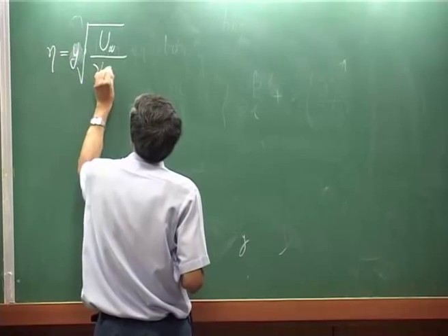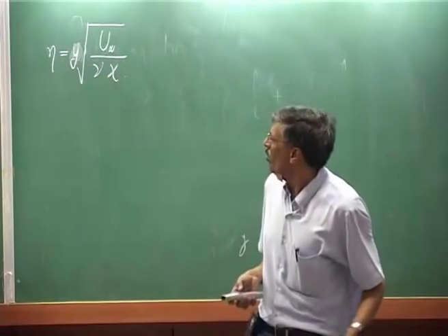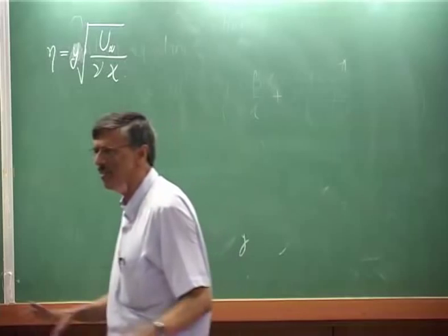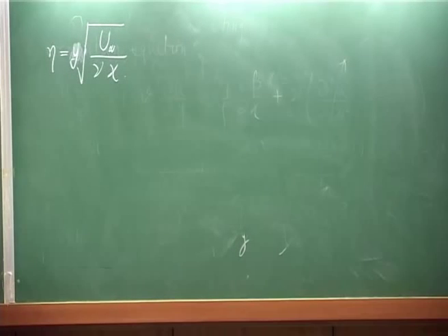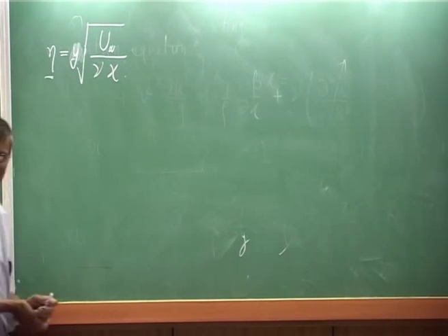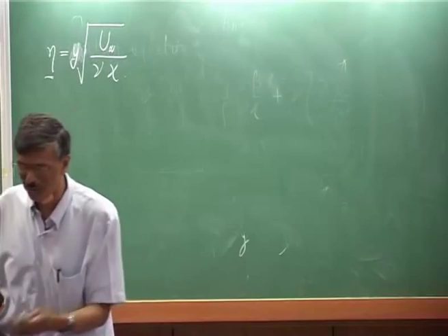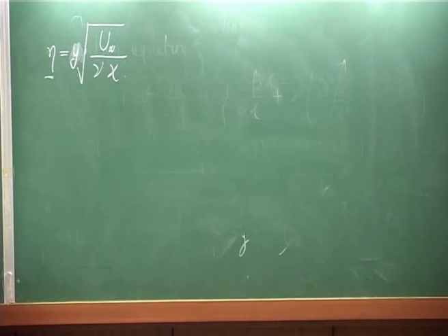So, what is the idea? The idea is the same as what we did with the spring mass system. Wherever we have a problem, we stretch the coordinate. The same thing: if a boundary layer is forming very close to the wall, for a very small thickness of y, you stretch it open, and that stretching is achieved through this. I do not wish to get into this. There is a formal subject called Lie group transformation. That is where you basically come out with all these similarity transformations. This is a very involved subject itself.